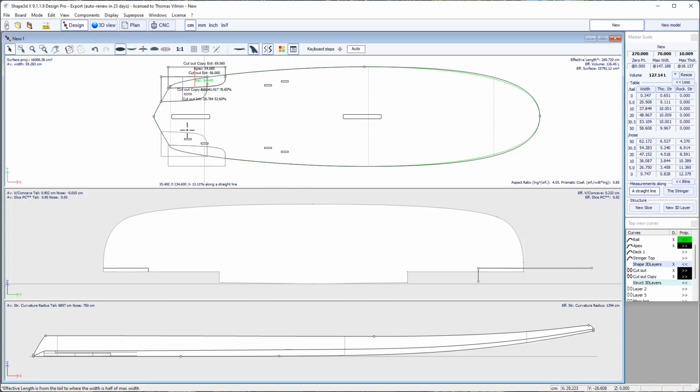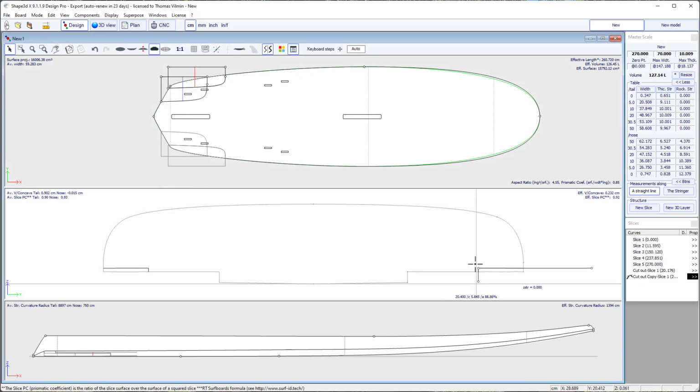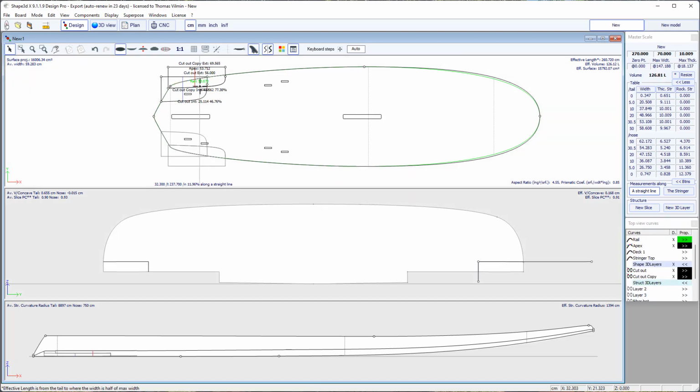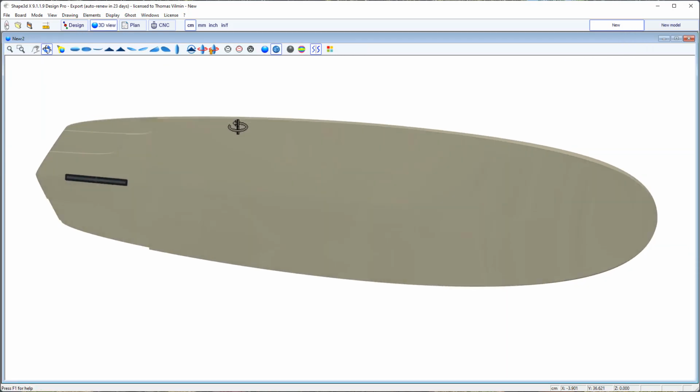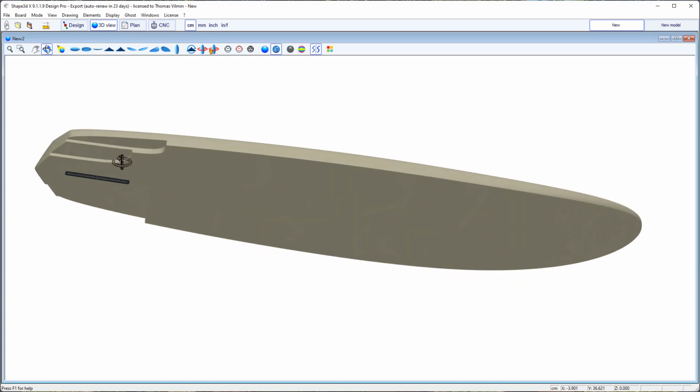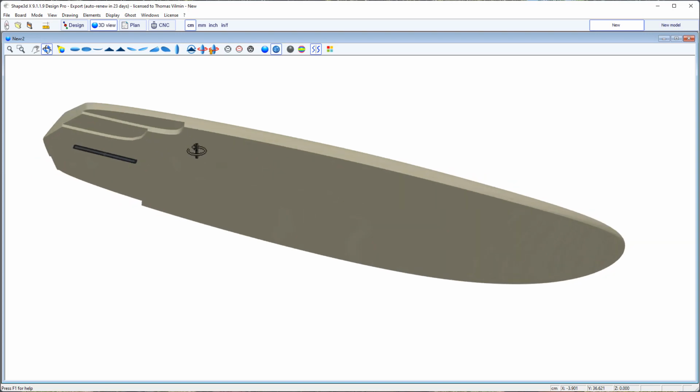And so this slice here is not mapped on the previous 3D layer, but on the original shape. And so at the transition, when it goes from previous 3D layer to bottom, you won't have any step, and you can accumulate different 3D layers to do multi cutouts without any problem.